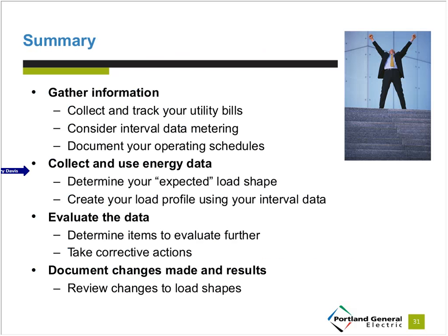You can look at those charts and graphs that will enable you to see what your typical usage is during the day, during the month, during the week. And once you've created those profiles, you can make some decisions on whether you want to try and make improvements. You could take a look at the data and evaluate, can I turn off some HVAC systems a little bit earlier, or can I turn them on later in the day?